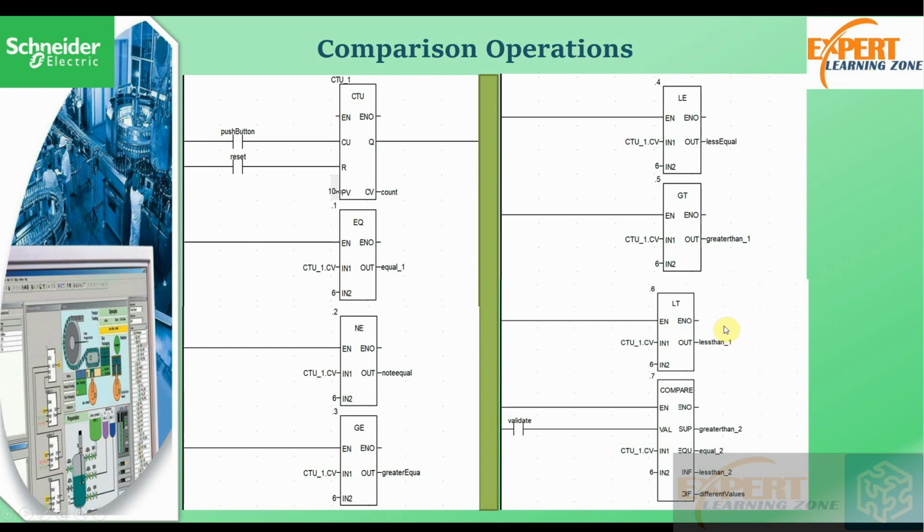So we use this a lot in process development when we want to track counts of maybe packets, maybe pallets, and we want to either turn the output off or on based on the logic. Maybe we want to stop the operation when the current count becomes greater than a certain amount, or turn on the output when the value is still less than or equal. So it depends on the application that you're building. You can use these different blocks.